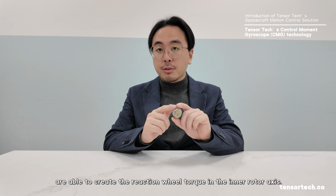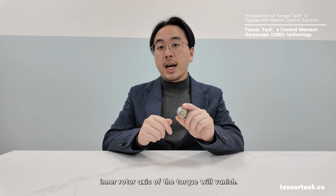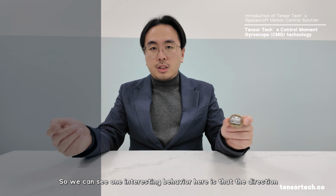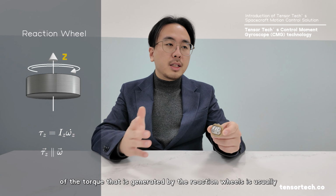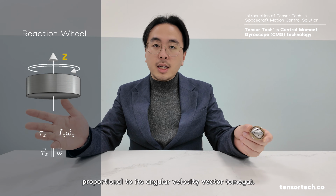Not all control moment gyroscopes can do that, only the CMGs that have variable speed capabilities, which are able to create a reaction wheel torque in the inner rotor axis. But for those CMGs that only have constant speed capability, this inner rotor axis torque will vanish. So one interesting behavior we can see here is that the direction of the torque generated by a reaction wheel is usually proportional to its angular velocity vector omega.